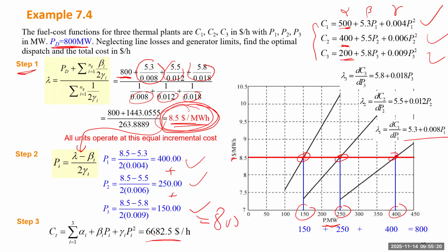So that is why you cannot have any unit be more expensive at this operating condition, because if they operate here, that's not equilibrium. If you ask this unit to operate at a more expensive condition, you are going to ask why you cannot decrease the price. If they operate at this condition, the other 2 units will be more competitive, right? They also want to go up. So eventually, they reach this equilibrium at the same price.